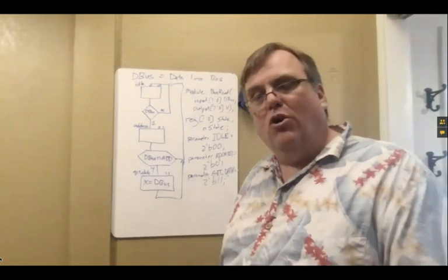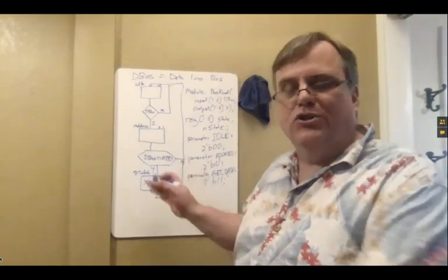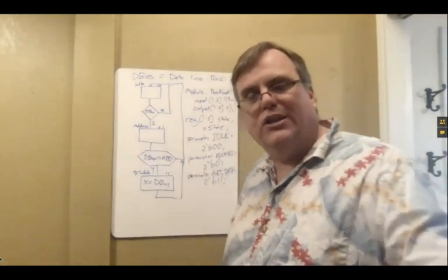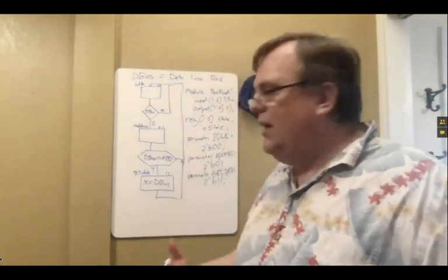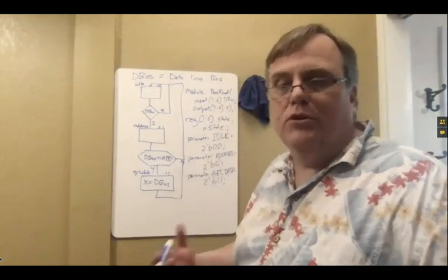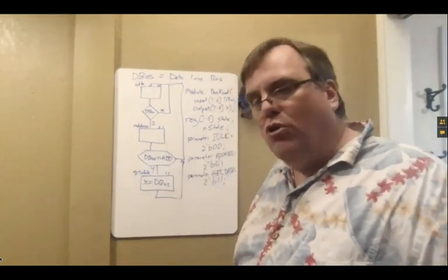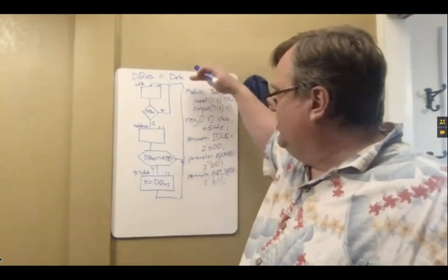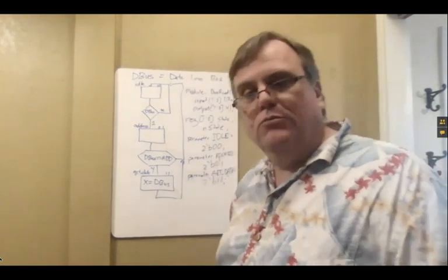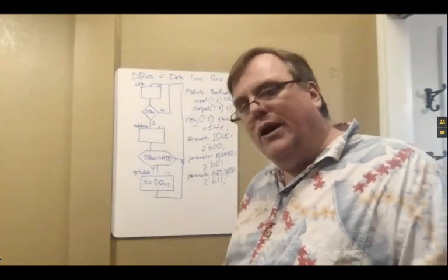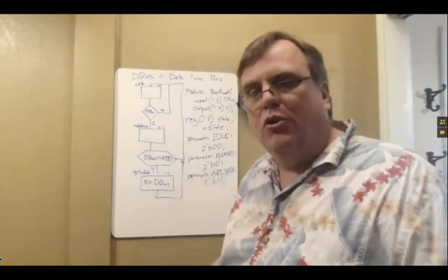So Verilog gives you a methodology. I don't want you to worry about it now. It's something we deal with in advanced digital logic, but it does allow you to override parameter values. Local parameters, you don't. So local params are completely internal, so they're theoretically protected from somebody ever making those changes. So I would pick a local param if I don't want them to be able to override.